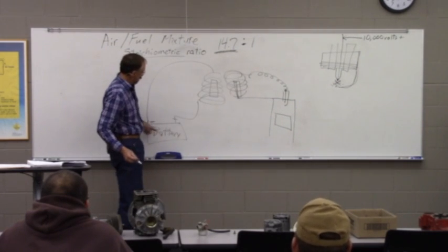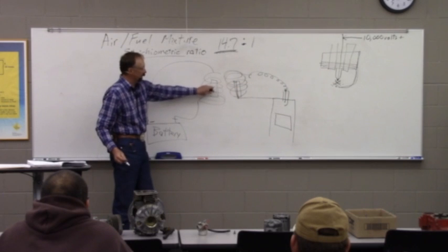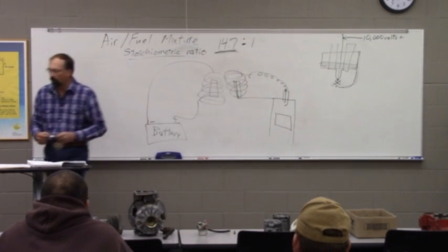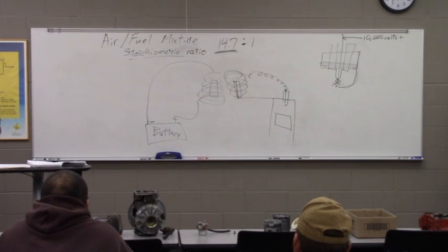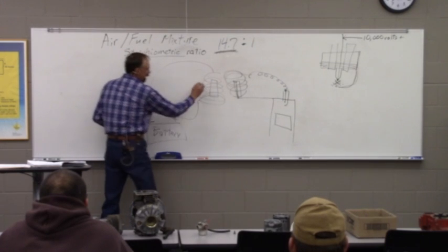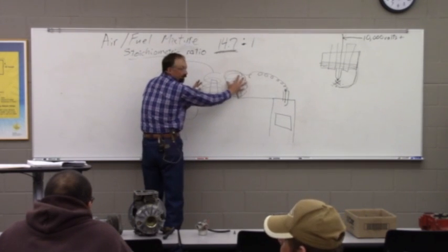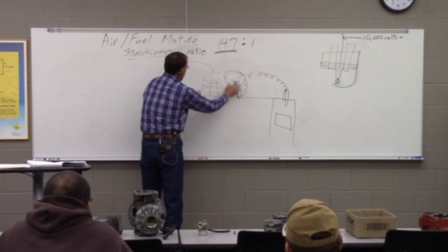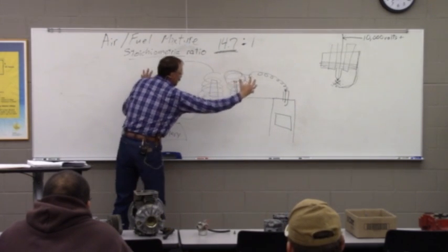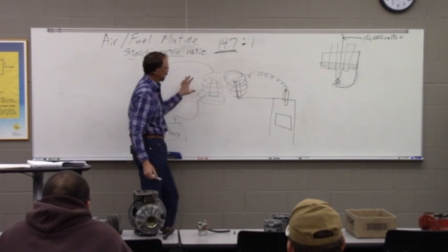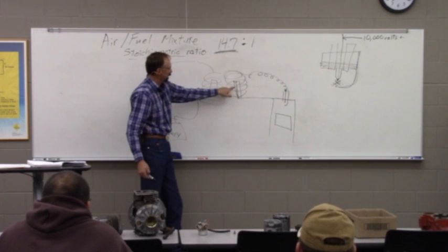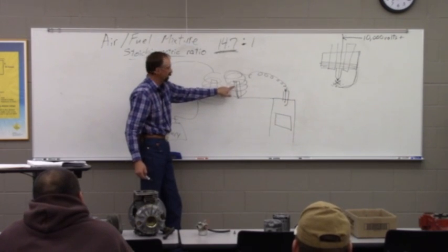So when we've got current flow through this, we've got a magnet here, and it's creating this magnetic field. I'm behind. I was supposed to have been done with this part by now. But we're creating this magnetic field, which is also occupying the space of this coil. When we break this, that magnetic field collapses, and a neat scientific fact is as it collapses, it produces current in this coil.